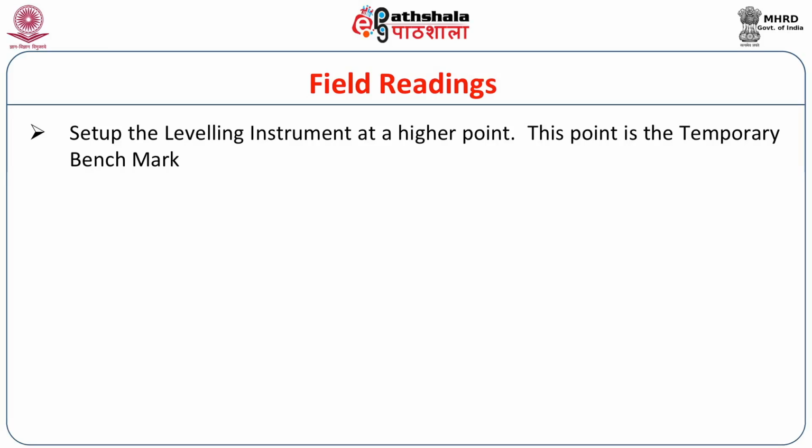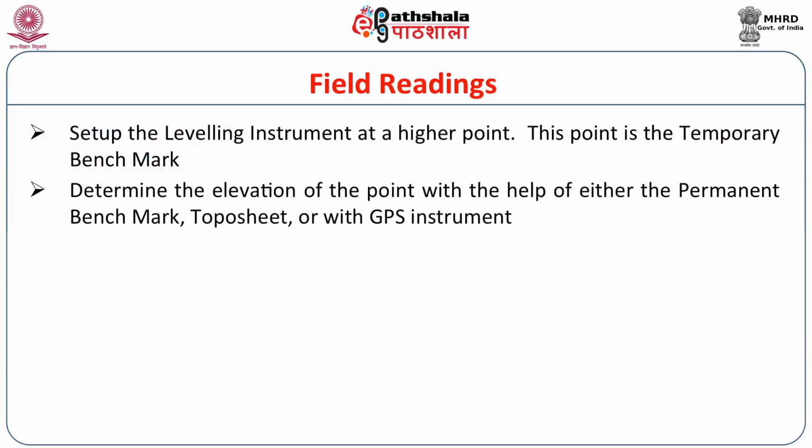What is a benchmark? Benchmark is usually the measurement that indicates the mean sea level at that point. So, to determine the mean sea level, we can use various kinds of methods. One of the methods is to use the topo sheet data, that is, on the topo sheets there are permanent benchmarks which are marked.